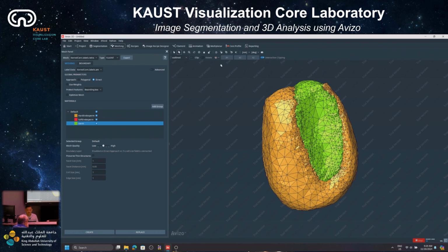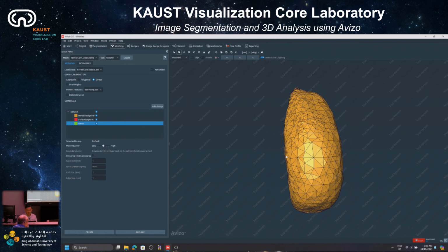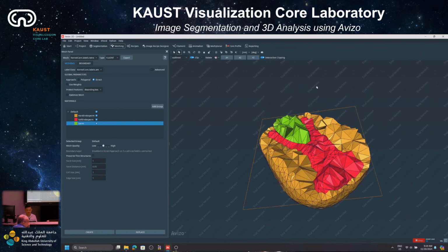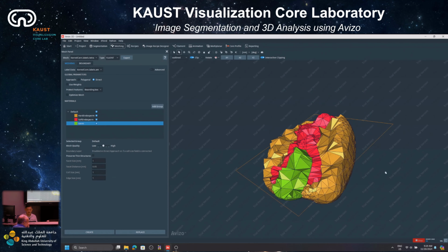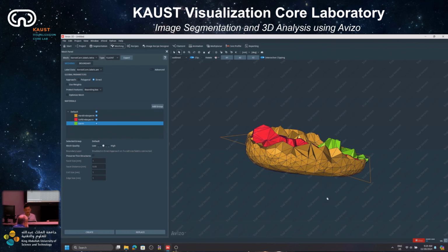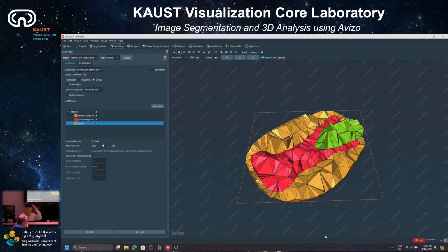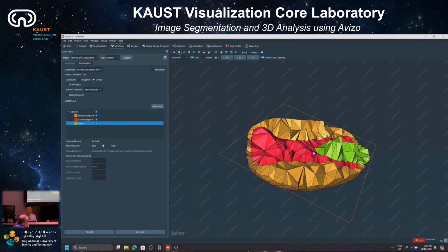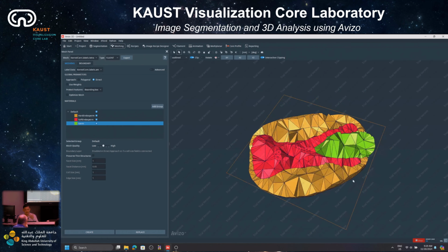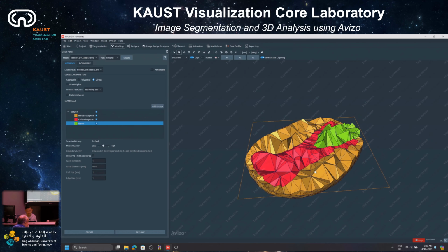On the 3D viewer here, we have the spatial clipping for this mesh. If you click on the clipping over here once, you can see that the clipping is spatial for the mesh in the meshing workroom because it doesn't cut flat, it just clips the tetrahedral mesh. I show you this just to show you that this mesh is not a 2D surface mesh, but a 3D volume tetrahedral cell mesh.